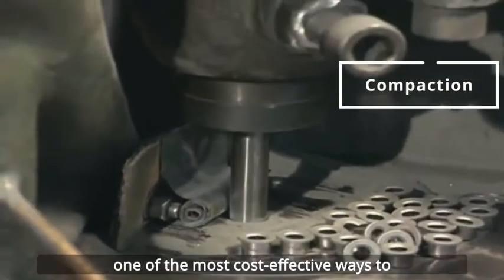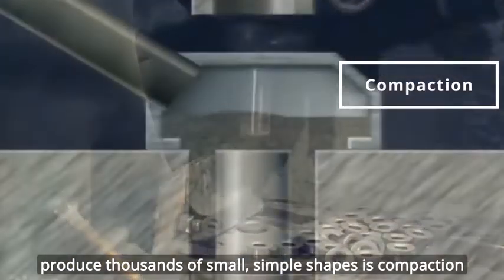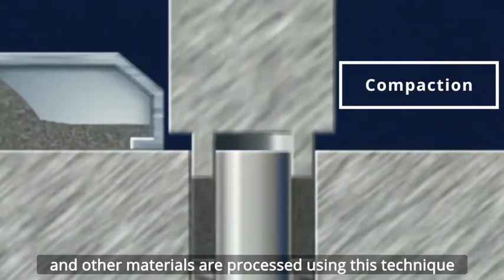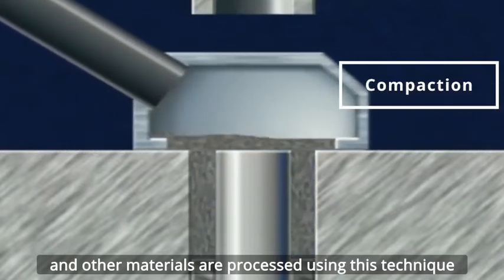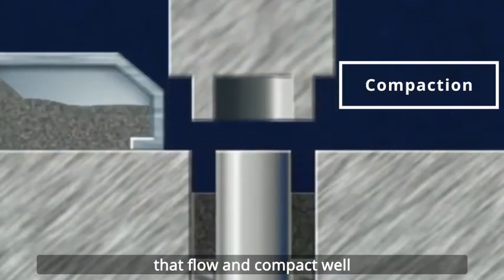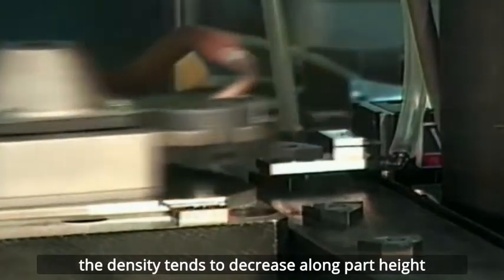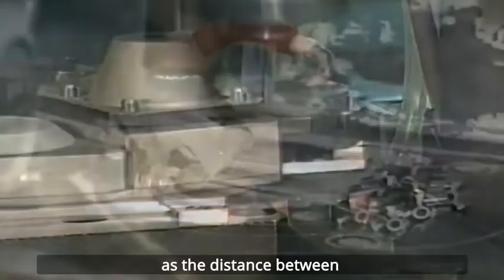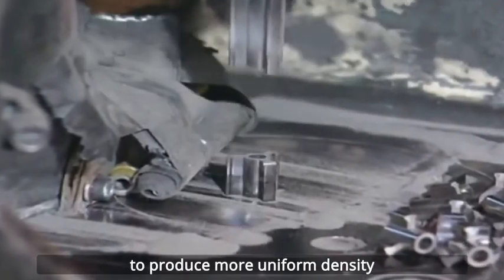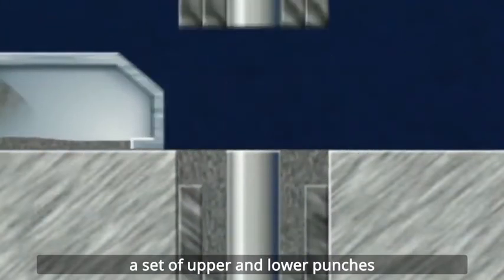One of the most cost-effective ways to produce thousands of small, simple shapes is compaction. Many electronic and magnetic ceramics, cement, and other materials are processed using this technique. Fine particles are in the form of soft agglomerates that flow and compact well. The powders are then compacted. The density tends to decrease along the part's height as the distance from the packing punch increases. To produce more uniform density, thick parts are compacted by a set of upper and lower punches.